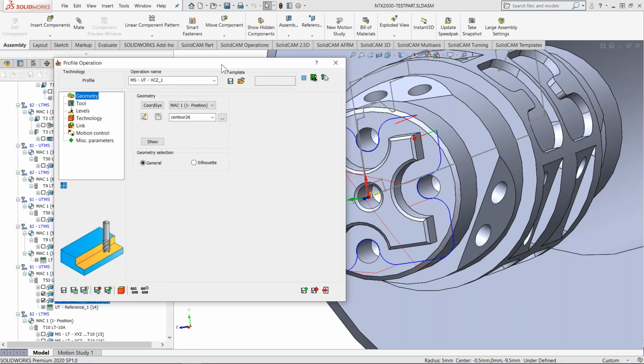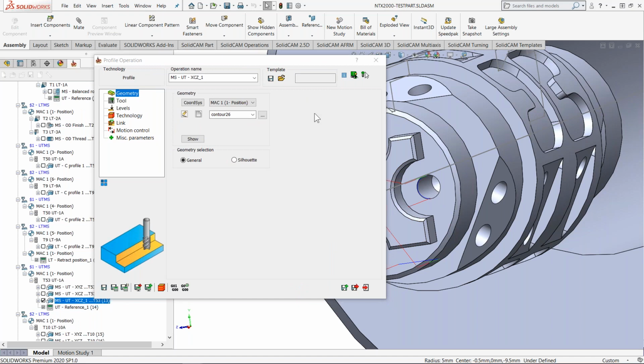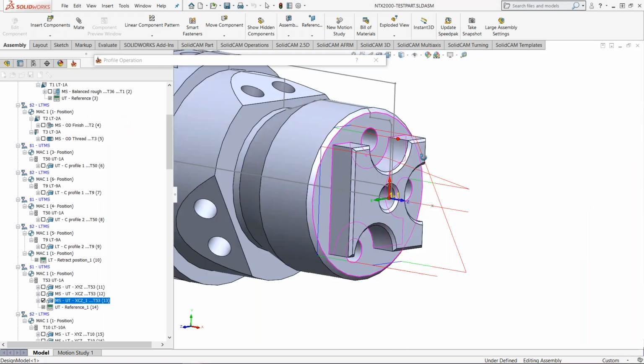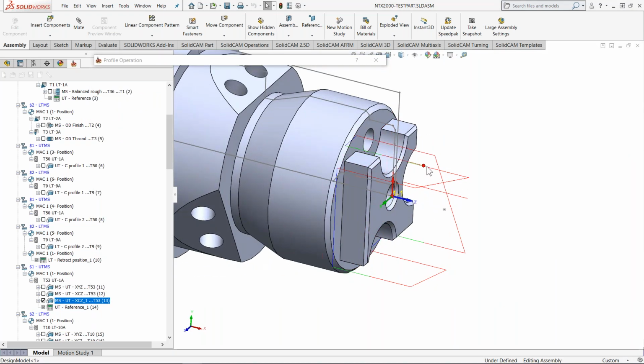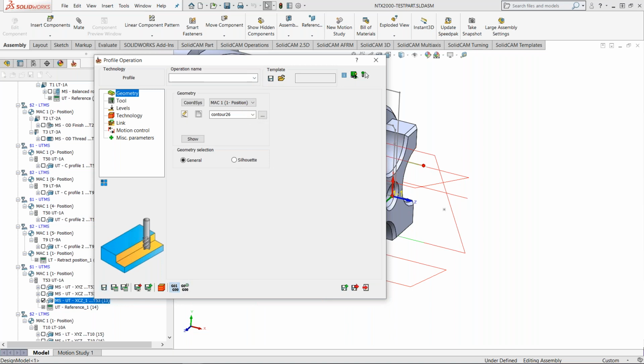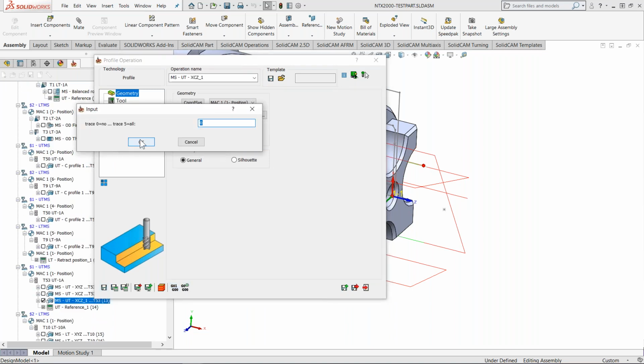And the rapid movements, let me turn off the previous job. The rapid movements in the previous post will actually be generated with a G1 with unnecessary G0 movements. So it will be, I would say, jerky motions, with many unnecessary movements. In this case, it will go straight ahead towards the next point. Let me just generate the G code and let's see the output.